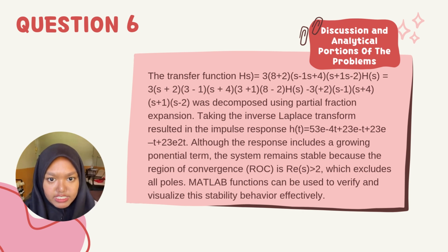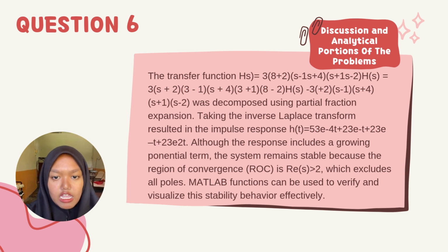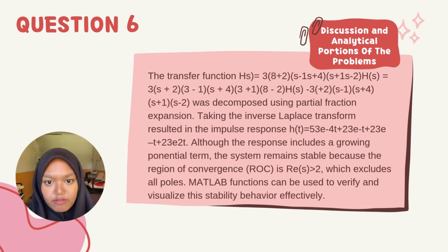The transfer function was decomposed using partial fraction expansion. Taking the inverse Laplace transform results in the impulse response. Although the response includes a growing exponential term, the system remains stable because the region of convergence, ROC, is Re{s} greater than negative 2, which excludes all poles. MATLAB functions can be used to verify and visualize this stability behavior effectively.